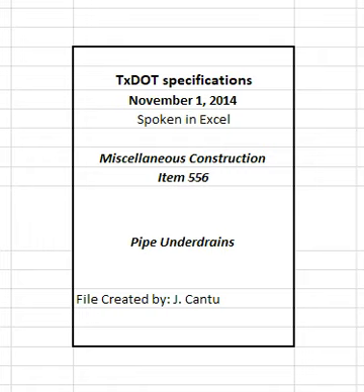Depth of trench, feet, and distance outside neat lines of pipe underdrains, feet. Depths of 0 to 6 feet require a minimum distance of 1.00 feet. Depths of over 6 to 10 feet require a minimum distance of 1.50 feet. Depths of over 10 to 15 feet require a minimum distance of 2.00 feet. Depths of over 15 feet require a minimum distance of 2.50 feet.